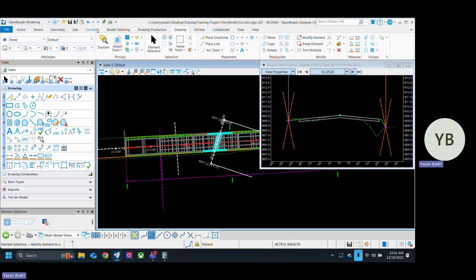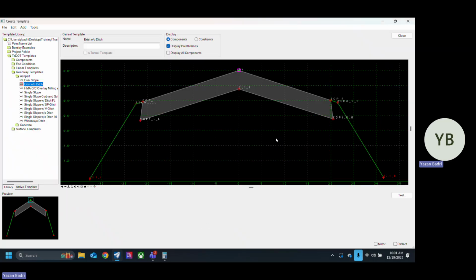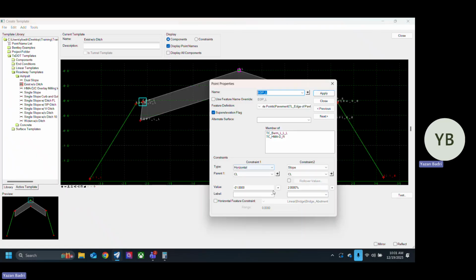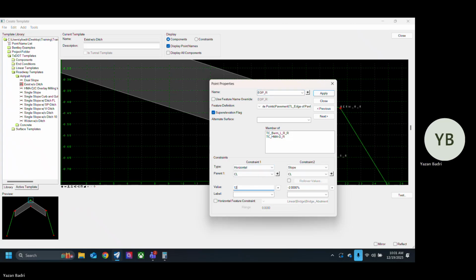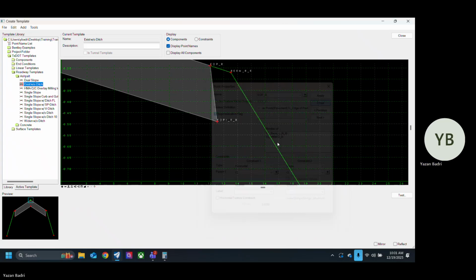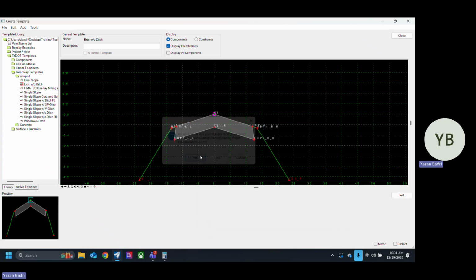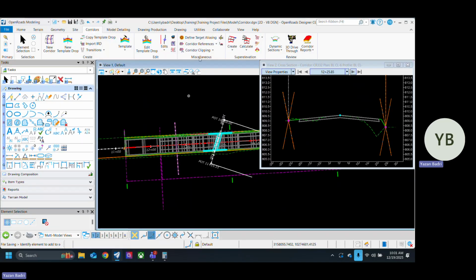What happens if the profile happens to be below the natural ground in an overlay? Will it still draw a constant depth? Sorry, can you say that again? So is everything constant thickness, even if the proposed profile is lower than existing ground at a particular section? Yes. Theoretically, it's not really an overlay.